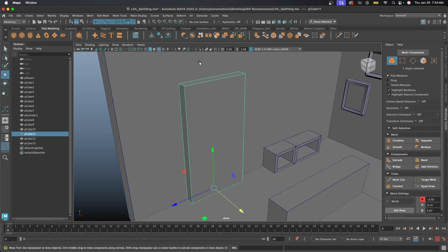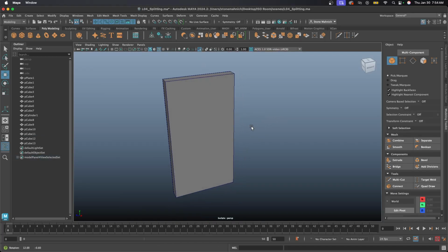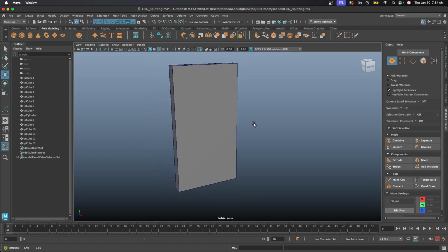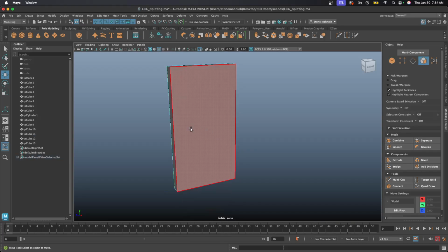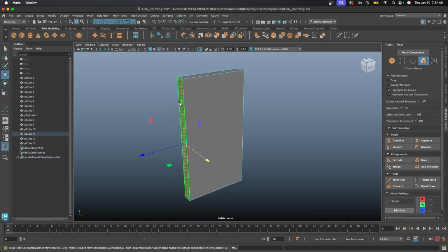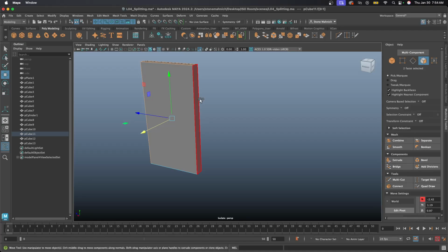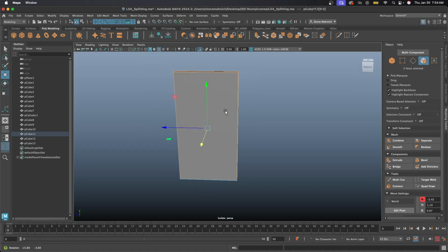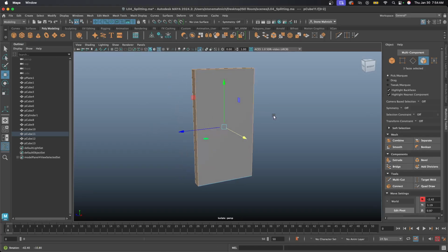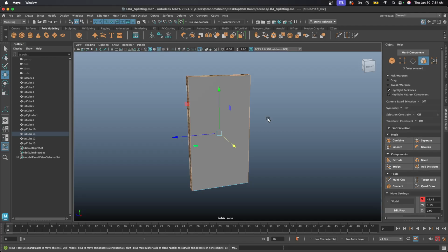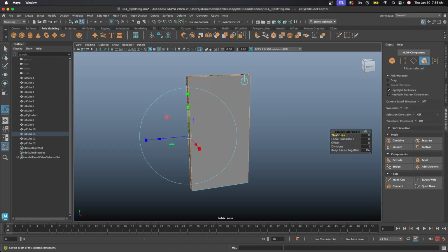Okay, now we're going to do one more, the door. So let's select your door. Let's isolate it. So we isolated the door. We're going to go to face mode, so you can click on the buttons over here, or the shortcut is right click hold, select your geometry, right click hold, go to face. You're going to select the left, top, and the right side. I did multiple selections with shift. So click, hold down shift, click, hold down shift, click. We're going to make a door frame, so let's extrude it out. So extrude, we're going to change the thickness.